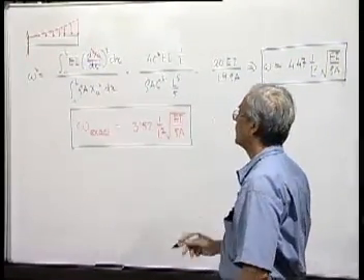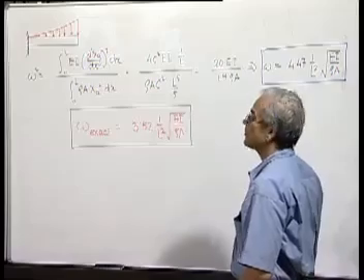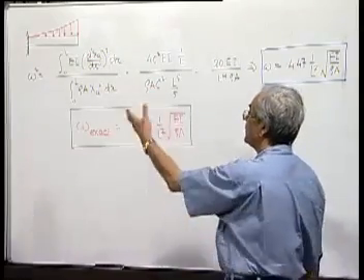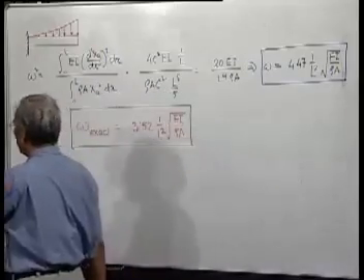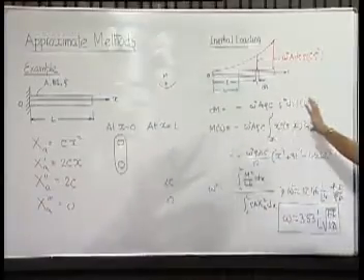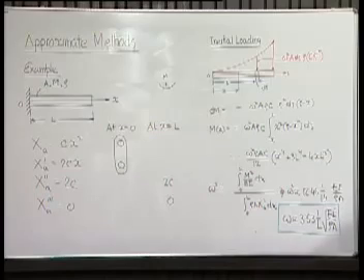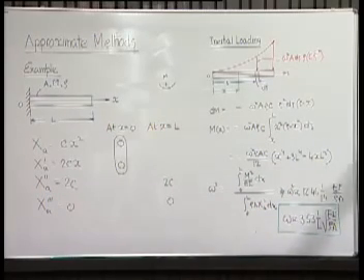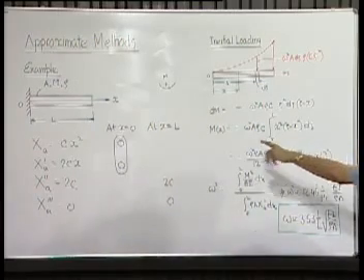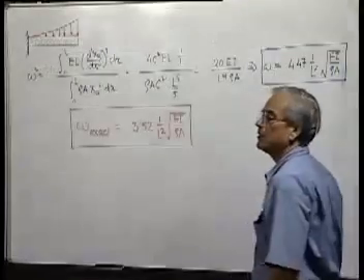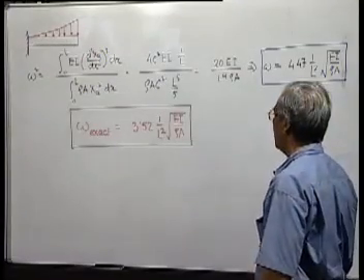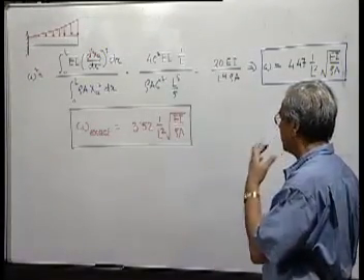So therefore, the accuracy can be substantially improved in Rayleigh's method if we use the moment expression directly, which is determined by finding out the inertial loading based on the assumed mode shape x, and that results in substantial improvement of the value of the result.